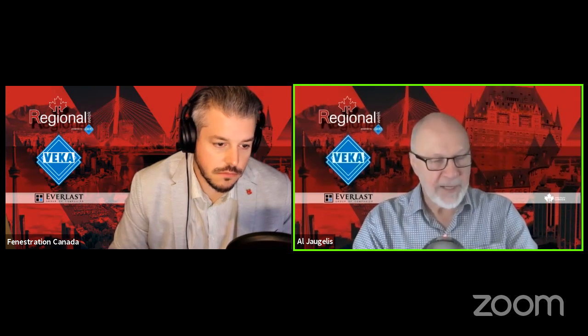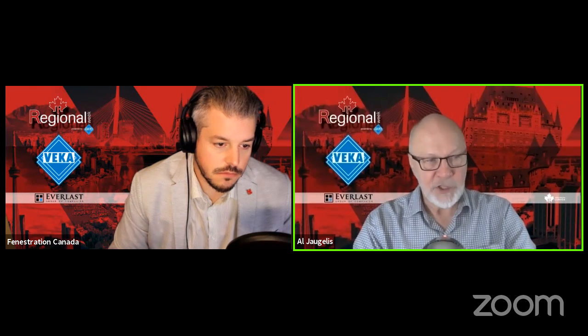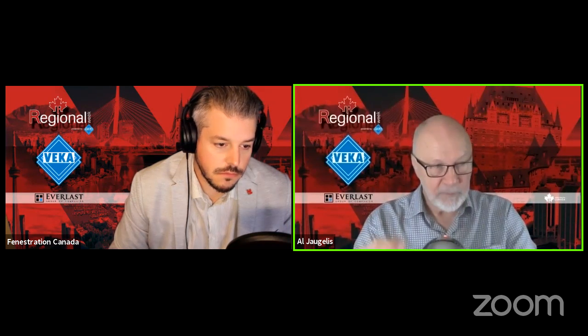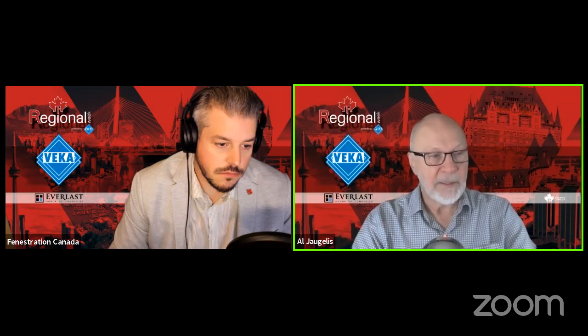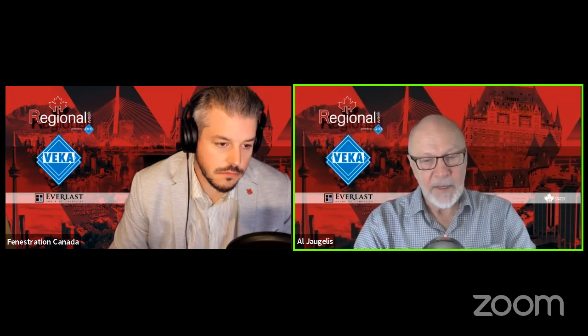There's a 1 in 5 chance any given year, a 20% chance that you're going to get that higher level of water penetration load coming to you. So from a water penetration perspective, it's probably wise to consider it open terrain. From a structural performance perspective, it may be safe to consider it a rough terrain situation.